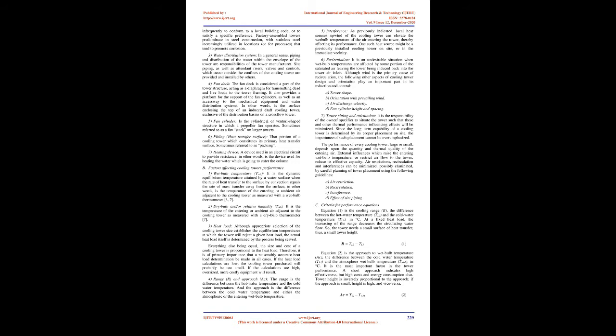4. Fan deck. The fan deck is considered a part of the tower structure, acting as a diaphragm for transmitting dead and live loads to the tower framing. It also provides a platform for the support of the fan cylinders, as well as an access-way to the mechanical equipment and water distribution systems. In other words, it is the surface enclosing the top of an induced draft cooling tower, exclusive of the distribution basins on a cross-flow tower.